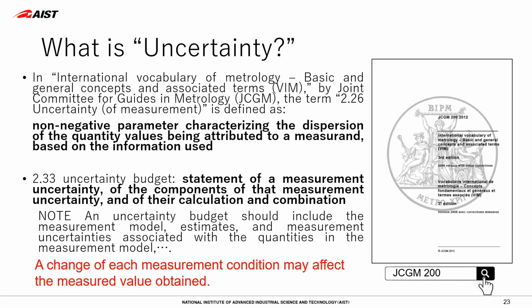When you carry out measurement, a number of conditions can be considered, as we have seen in the last few slides. In addition, no matter whether you are aware or not, some other conditions may affect the result. We try to realize the definition by controlling the conditions, but the controlled condition may have variations. Measurement uncertainty is a kind of combined effect from such variations.